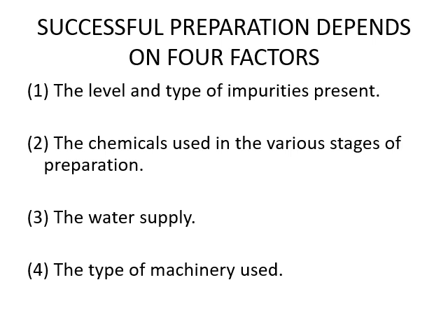The central goal of preparation is the removal of both naturally occurring impurities and those which are added during yarn or fabric manufacturing. The dyeing process can be performed on textile fibers, yarns, fabrics or garments depending on the properties or for cost control.